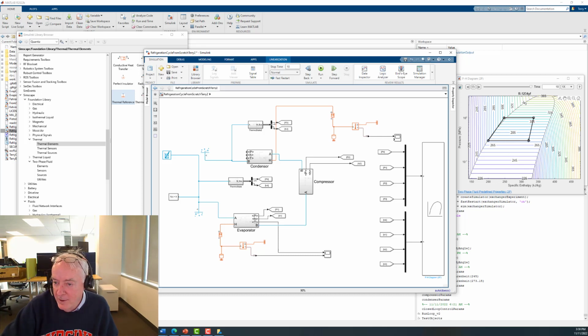Aaron had a huge problem with the location of this point still being in the two-phase regime. Basically, that it's still boiling. There's no way in the world you're going to send a combination of boiling liquid and vapor into my compressor. You break compressors by doing that. So one of the things he explained to me is you have to evaporate the fluid in your evaporator. It has to be pure gas. And so you need to be on the right side of the boundary to the dome right there.